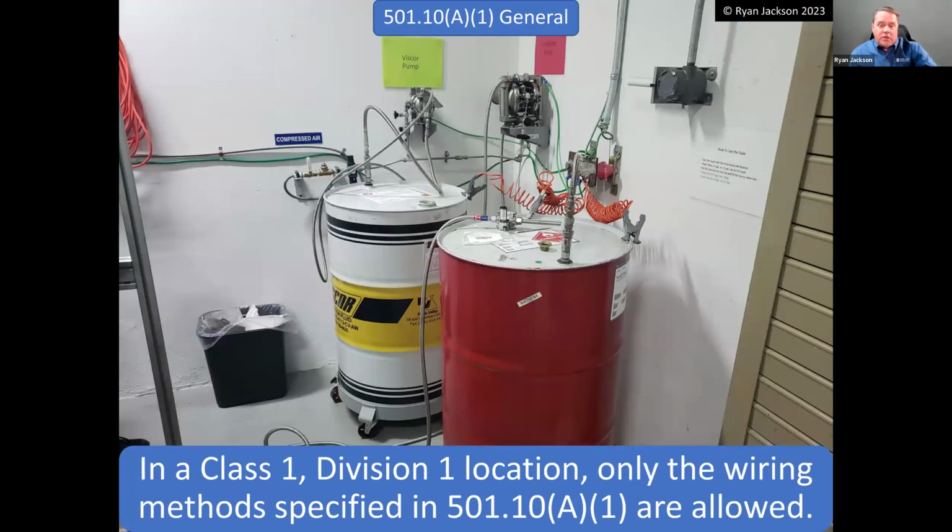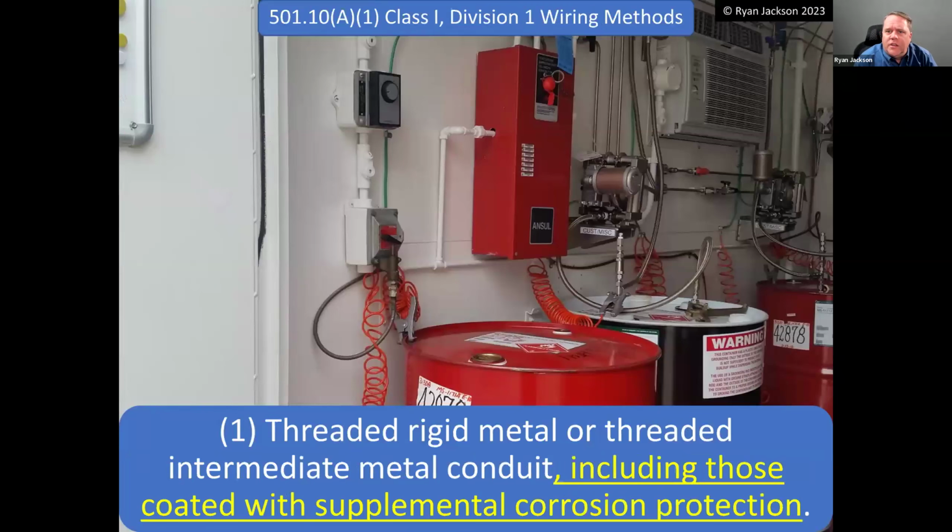Another example of some specific applications might be if I'm doing hazardous locations, right? What kind of wiring can you put in a room that looks like this? Well, the answer is not much. When it comes to this, we're pretty much looking at using threaded conduit, right? Rigid and IMC. There's a couple of other exceptions as well, but certainly rigid and IMC are going to be the most popular methods in what we call a class 1 location like this.